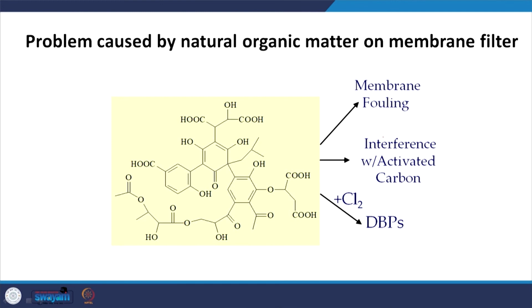And one other aspect is, we talked about the issues with respect to natural organic matter. It will interfere with activated carbon, and with chlorine it will form disinfection byproducts. Here also it is going to cause an issue, as in membrane fouling. It is going to foul the membrane pretty quickly. Yes, that is something to keep in mind.